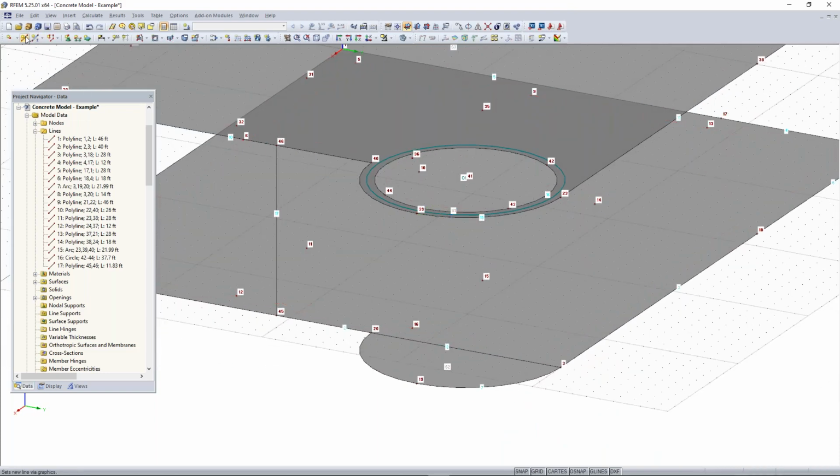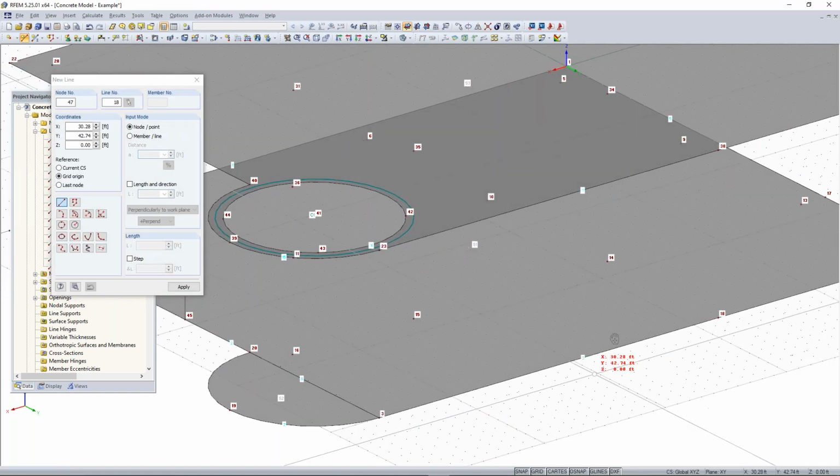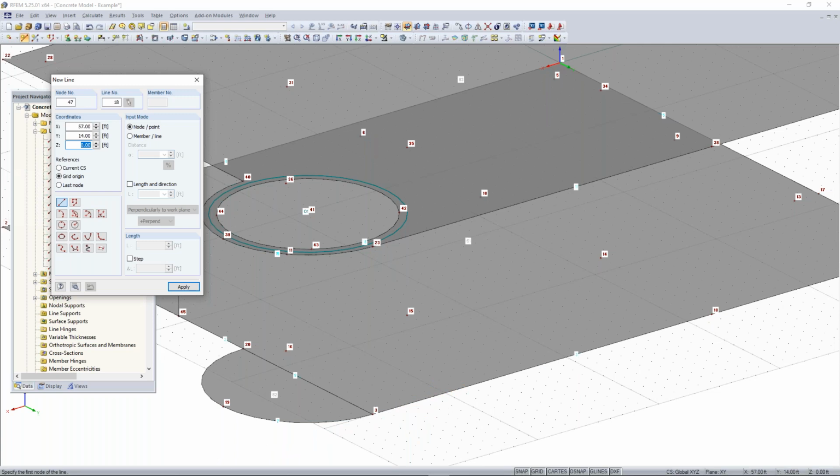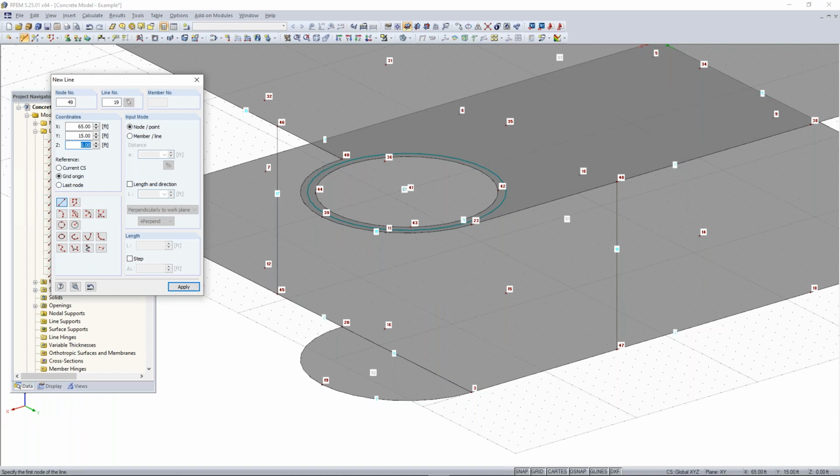And now I can just draw another line on the other side to define our second wall here. And this one, I need to draw a line from 12 feet from node 3 here. So that's going to be at the coordinates 34, 40, 0. And then I just want to draw this line all the way up to the ceiling slab. And you can see again, it snaps perpendicularly to the top there. Pretty easy. Then I can right click, and now all we need to do is connect nodes 20 here to node 40,